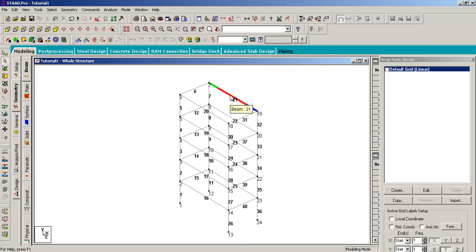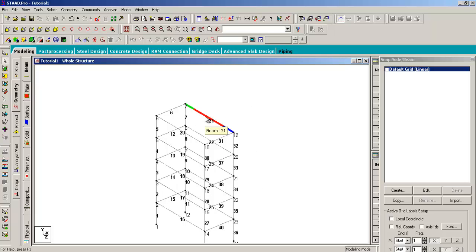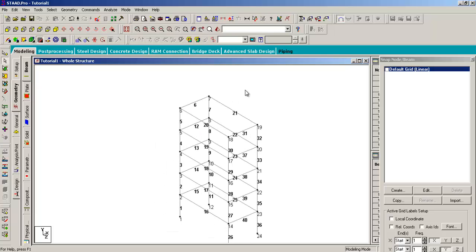So like I had told you, if we hover over any beam, we have 3 colors and the distance is calculated from the green part or the green end of the beam. I want to add some midpoints in these beams which are parallel to the z-axis, like 21, 20, 19, so that we have a square structure, square slabs on the roofs and floors.